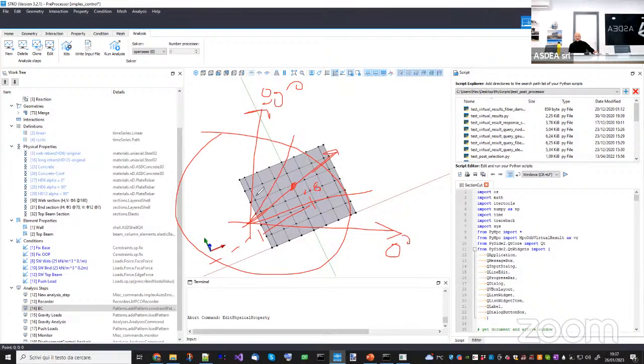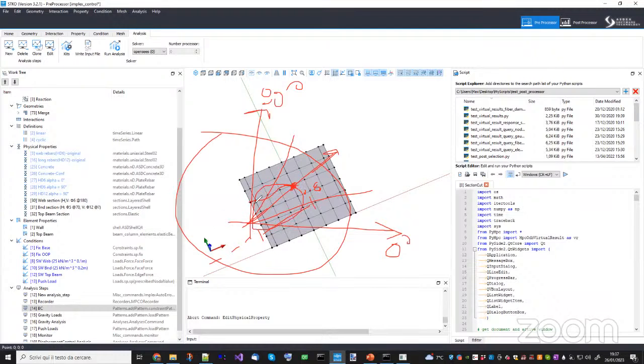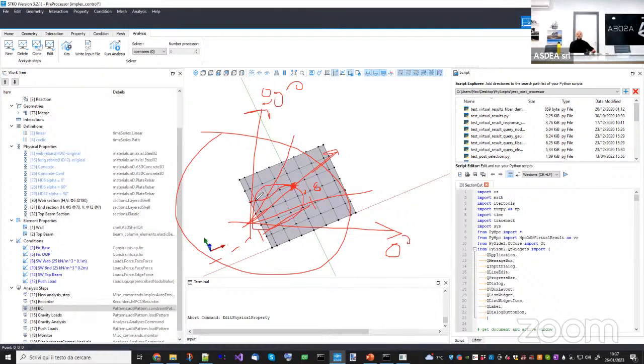Now the other cracks do not experience any damage due to the direct stress that you have here. But as I told before, we have this smoothing angle. With the smoothing angle, I smooth the damage around the neighboring cracks. It is difficult to represent in 3D, but if I flatten this from 0 to 90 degrees and put it in a graph with damage here and the degrees here, I damage instantaneously this point to this value of damage.